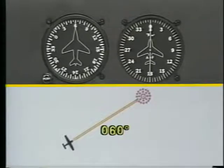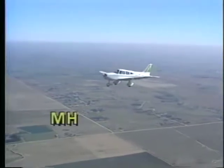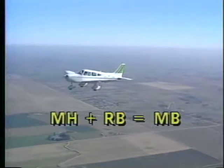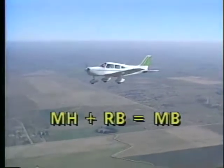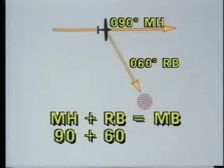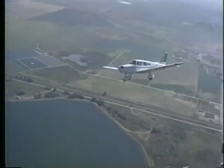At the completion of the turn, the ADF will be pointing toward 0, indicating the station is directly ahead. If you're flying a magnetic heading other than north, you must add your magnetic heading to the relative bearing to find the magnetic bearing which will take you to the station. For example, let's assume your magnetic heading is 090 and your relative bearing is 060. When you add these two together, you get a magnetic bearing to the station of 150 degrees. To fly to the station, in this case, you simply turn to a heading of 150 degrees.